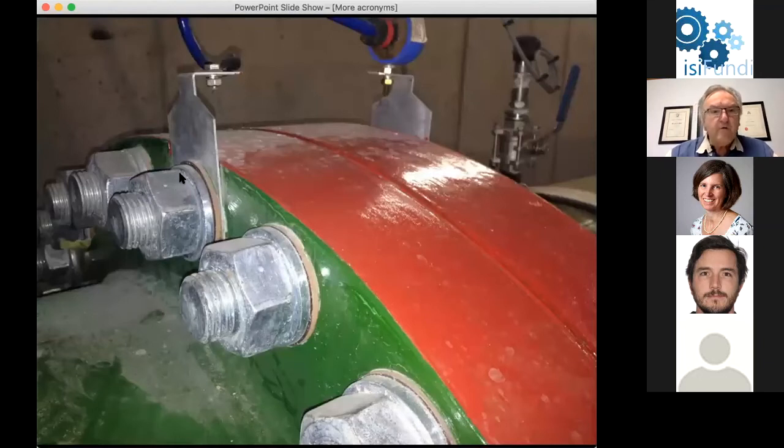Here's a photograph of what you can see of a kit on a flange, and there you can see an insulating washer. What you cannot see is that on the stud going through here is an insulating sleeve, and in between the two flanges is an insulating gasket. This whole system is then protected by a surge protection unit, which is located across the top. It's a spark gap, which allows transients from lightning or switching surges to be safely conducted.